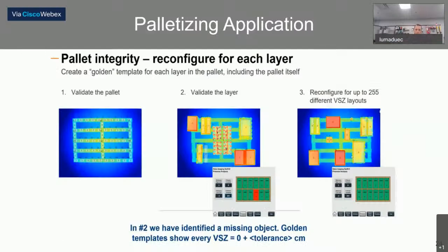So palletizing application is a perfect fit for the Swifty. You see the 3 different layers. First layer, multiple sensing zones all across that surface to ensure there's nothing there to affect the integrity of the stack. Then each layer after that has known points and heights. So if any one of those is out of line, I get an alarm output here.